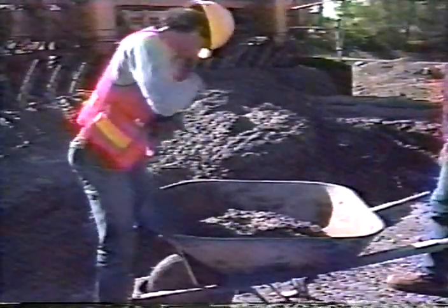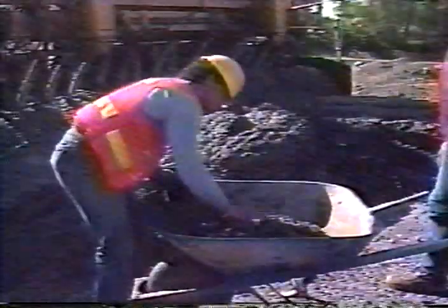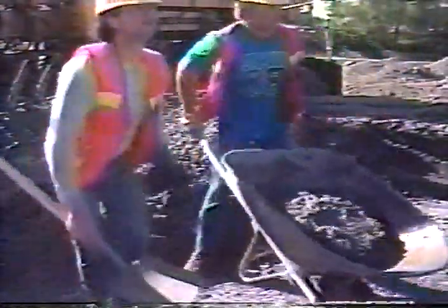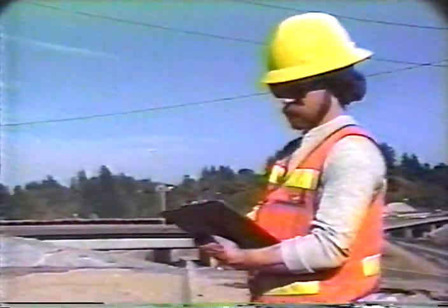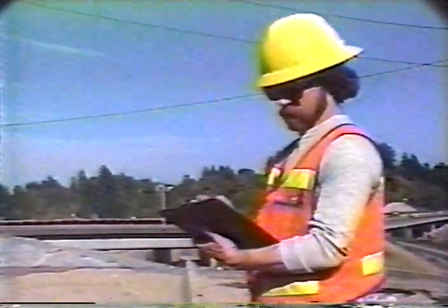The thermometer is inserted into the fresh sample so that the temperature sensing portion is submerged at least 3 inches. The concrete should be gently pressed around the thermometer so that the air temperature does not affect the reading. The thermometer is left in the concrete for 2 minutes or until the temperature stabilizes. Then the temperature is recorded. The measurement must be completed within 5 minutes after the sample is obtained.